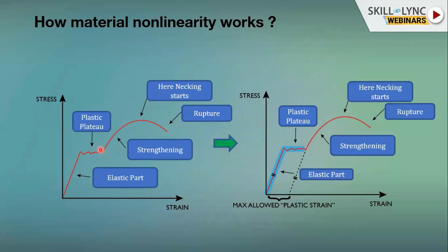But this time it strengthens the deformation. Once the permanent deformation is set onto the material, it strengthens based on the strain energy. That's what you must have heard about the terms called work hardening, strain hardening. It depends on the strain rate, the rate at which the strain gets developed over a period of time.